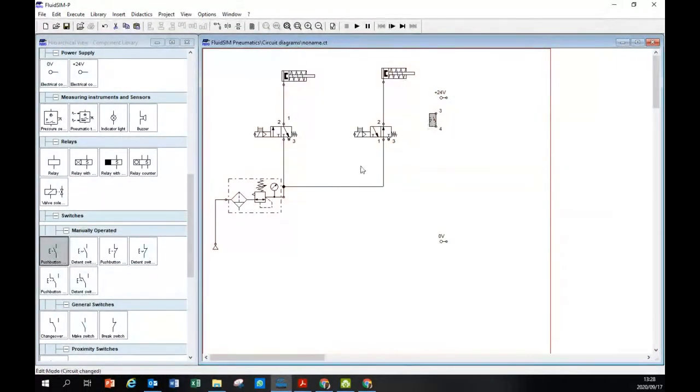I'm just going to put the relay there. Connect like that and connect there. Putting my stuff straight, orderliness is very important in this. So this is a switch, right? It's a push button, right? It's a make, also known as normally open.